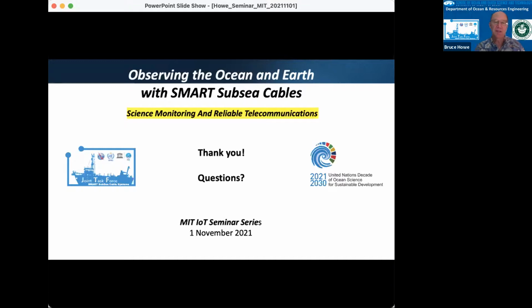Yeah. So the temperature and the accelerometer are reasonably well positioned from a calibration and a very small drift point of view. The pressure sensor, the current best pressure sensor, does have drift, and it should have oceanographic calibration, cross-validation, if you will.